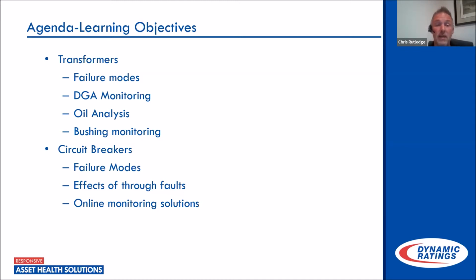We'll talk about DGA monitoring, and with that DGA monitoring, the oil analysis, which is critical to determining the true life you have remaining of that equipment. We'll also look at bushing monitoring, as that's one of your larger failure modes.